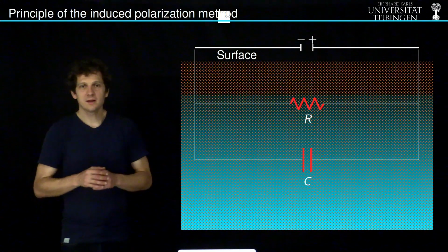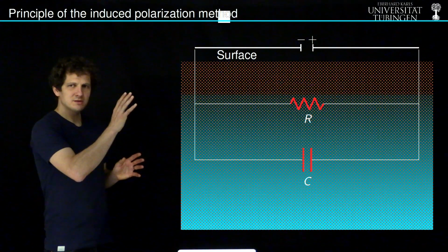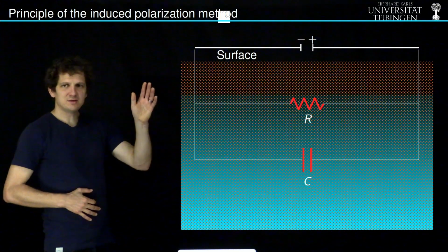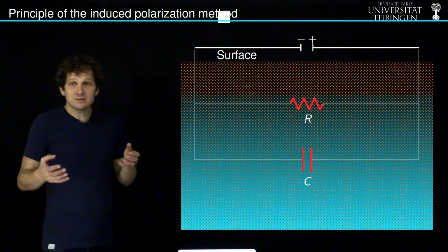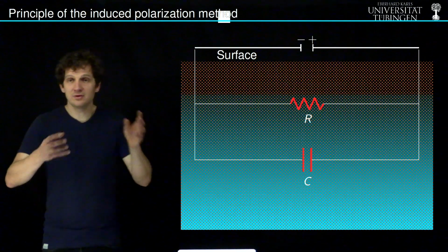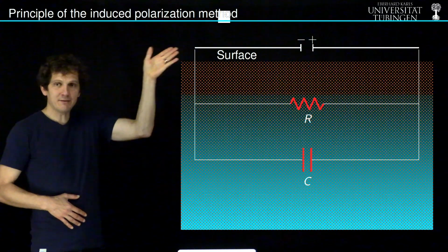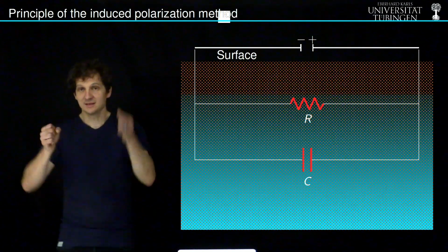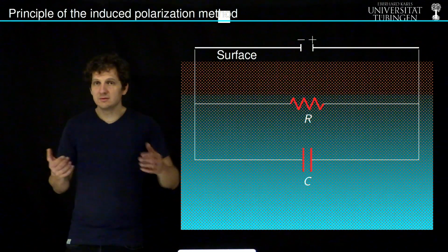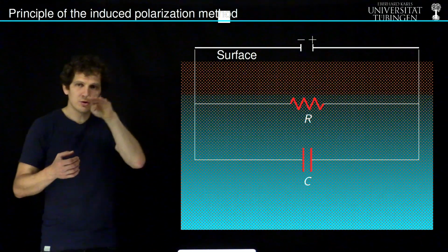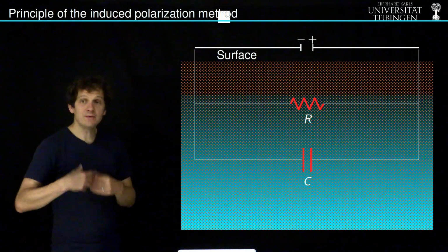Now the question is, how does induced polarization change the resistivity mapping? The way we represent that is with the simplest possible electrical circuit. If you remember how we started the resistivity mapping, we started with this upper circle. We have a direct current source, a battery with a plus and a minus connection. Metal sticks into the surface, we use them as a current source, they induce current flow, and we represent that current flow here in the upper branch flowing over an ohmic resistor.